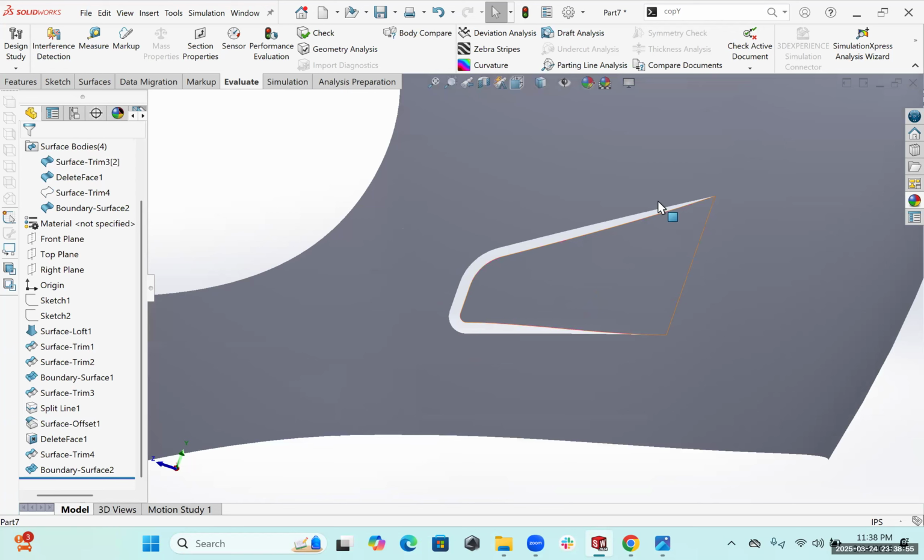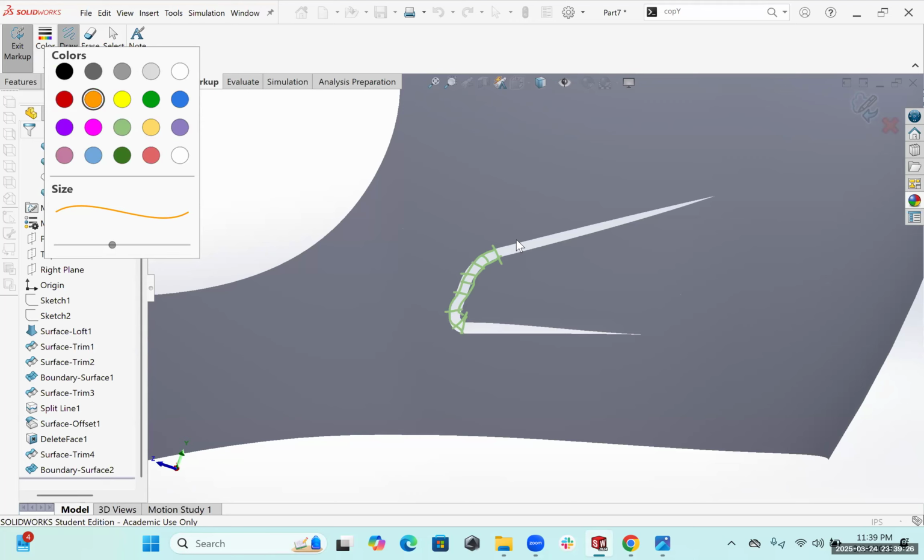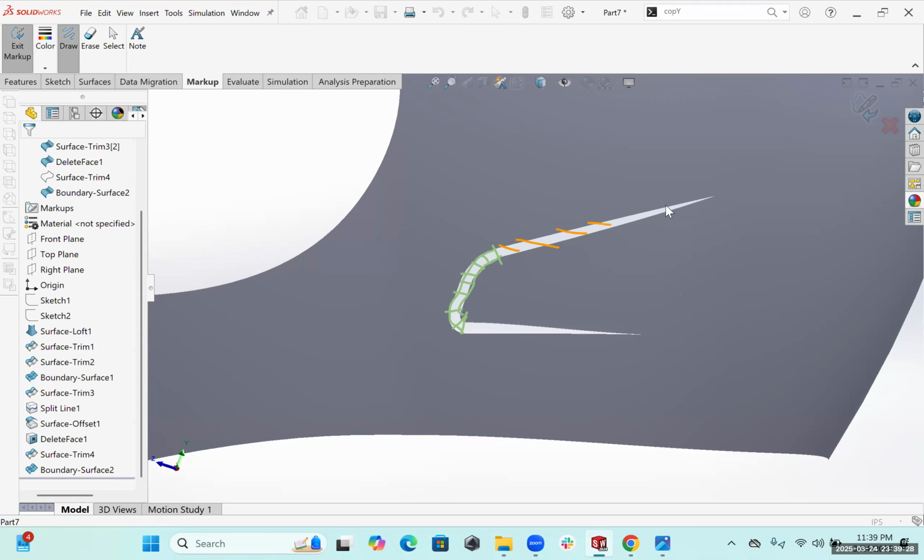Whenever we have sharp edges like this, they're not ideal for making surfaces. So what we would do is come in and create a boundary, because this form and this form are offset, so they have the same form. So we can create a really nice boundary here. And then we have the whole perimeter. We can fill the other surfaces. So then this one we can just fill surface. And that would take care of each corner.